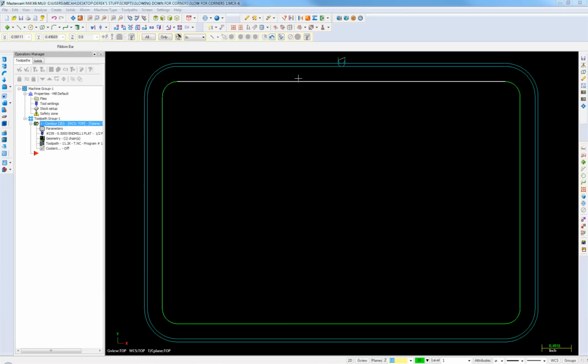Great. So as Derek said, today we'll be talking about several ways to adjust the feed rate of your CNC machine to accommodate the corners of your part. This was something I had never really thought about before Mike suggested it for a webinar. CNC machines are well known for their accuracy and speed, but when asked to change direction quickly, like going around a sharp corner, the accuracy can drop off noticeably due to the momentum of the machine in one direction.